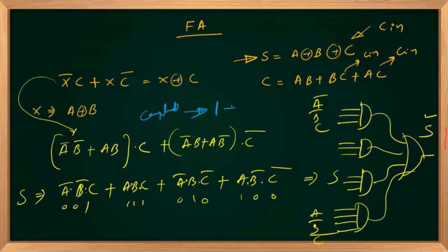Then we should produce the AND gate output product terms, and all these AND gates are operating in parallel, right? So this is the second gate delay, one AND gate delay. One corresponds to inverters, another corresponds to the AND gate.